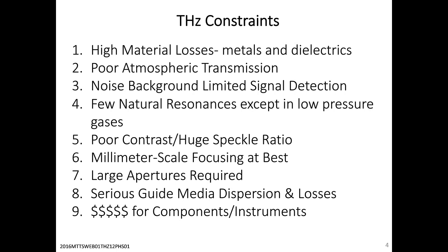I mentioned that we can do spectroscopy, but it turns out that at the atmospheric pressure environment we're in, the normally very narrow band molecular signatures that people are looking at get pressure broadened into quite wide bandwidths out in the gigahertz range, where the natural resonance might be a megahertz or two. And so that hurts when you're trying to identify particular gases in a high pressure environment. Or in liquids and solids, it's even worse.